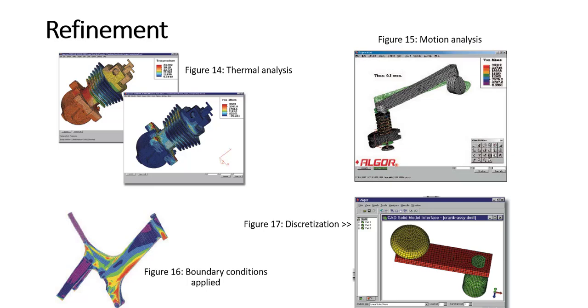The FEM processes the 3D computer models as input through a process called discretization or meshing, like Figure 16, and the continuous 3D solid model is changed into a model comprised of multiple polygon shapes such as rectangles and triangles, which are called elements.